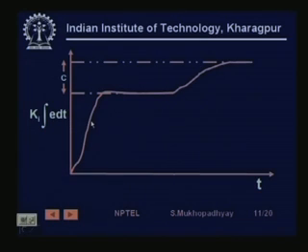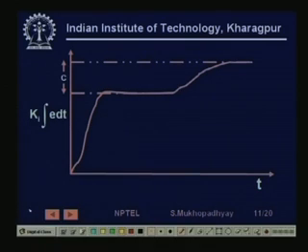So exactly this is what happens. Now you see, if you put the integrator, what happens is very interesting. This bias input which was previously coming now comes automatically. That is the integral output which I was talking about; it increases till it can, then it goes to 0, and then if you change the set point again from here to here, again some error will be created and it will again integrate and will generate just enough output such that it can be sustained without the error.